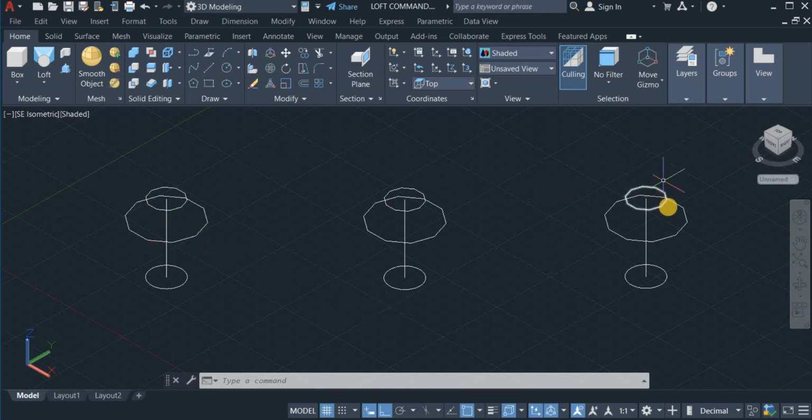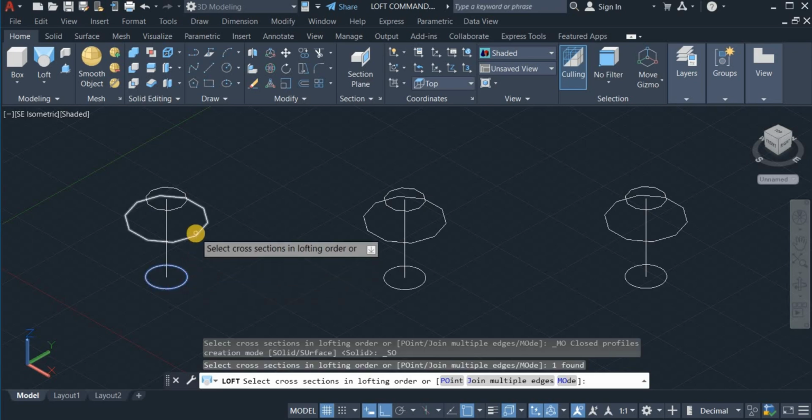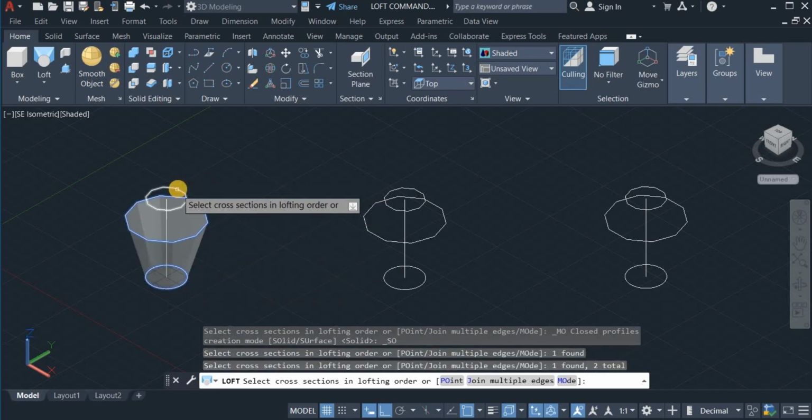Okay, so here are three setups here. You can see that you have three geometries here: a circle, a polygon, and also a smaller polygon. They are all the same and arranged in the same manner. So I'm going to loft these three together in 3D surface and in 3D solid. So you see how it is done. So I'm going to click on loft command again, then loft this. Now follow the order. This is first, loft to this, and loft to the third one up.